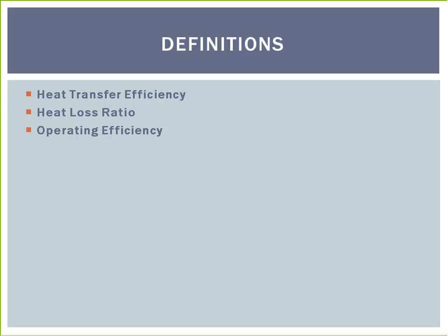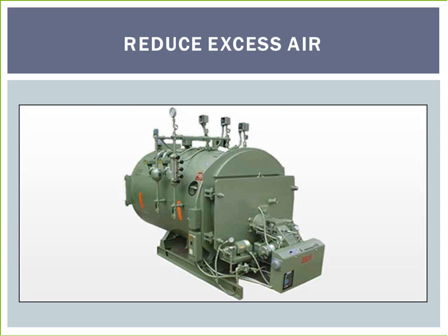Since a boiler operates most efficiently when it runs constantly or at full load, the trend of current technologies is to have several smaller boilers managing supply water needs instead of one large unit. This way, each boiler operates closer to optimum efficiency when they are called on for heat. Next, we will go over some various ways that boiler efficiencies can be improved.